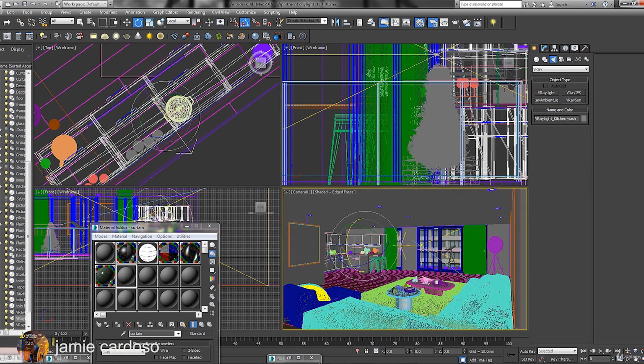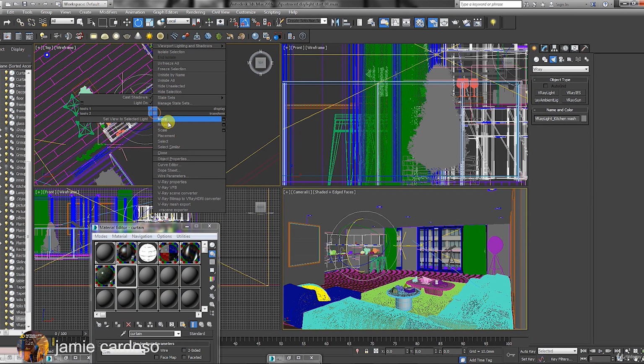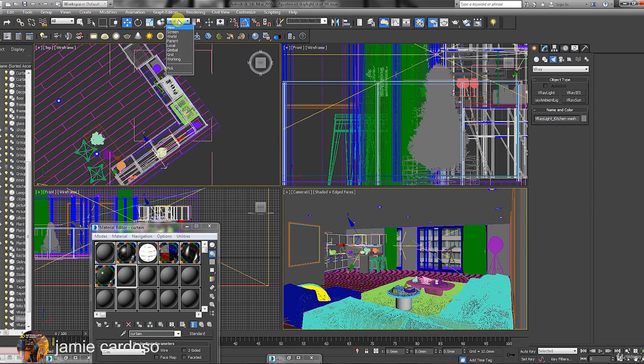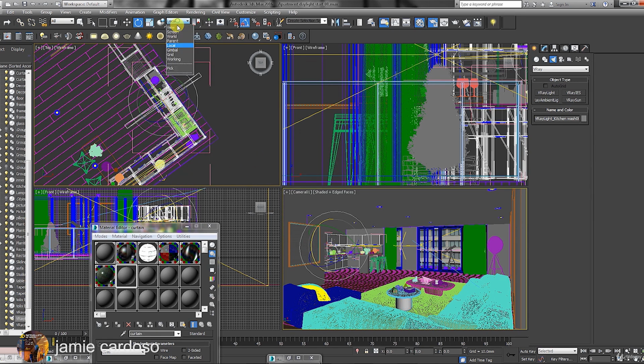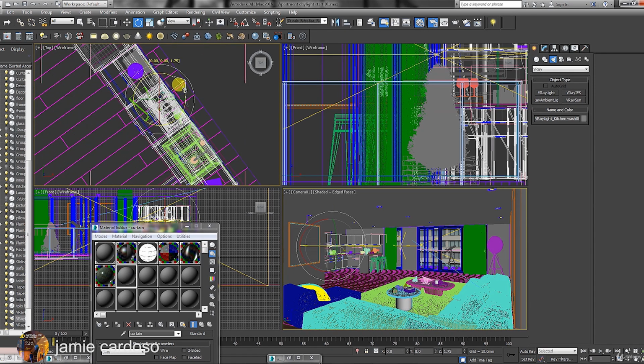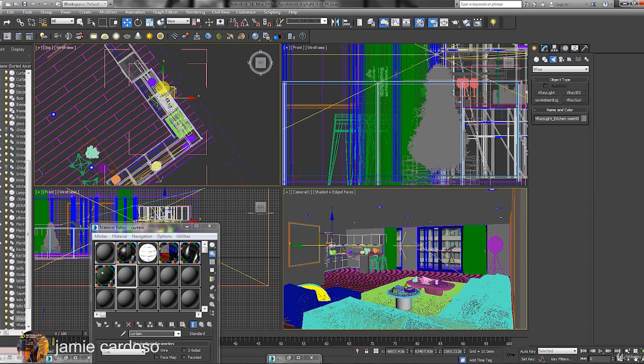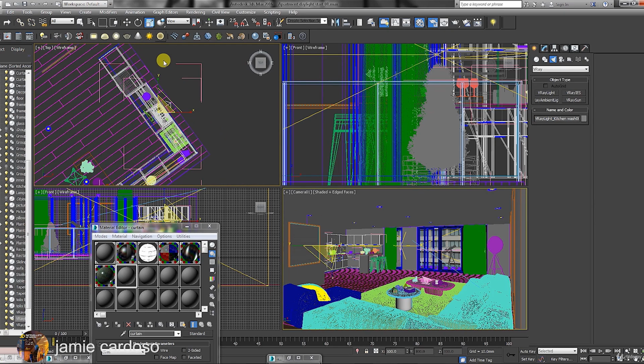We can copy instance the lights along the cupboards by holding down the Shift key and moving the object. Instance lights whenever possible, as it reduces the render times drastically. We can also use the Scale toolbar to reduce the size of instance lights to fit areas without affecting the other instance lights.